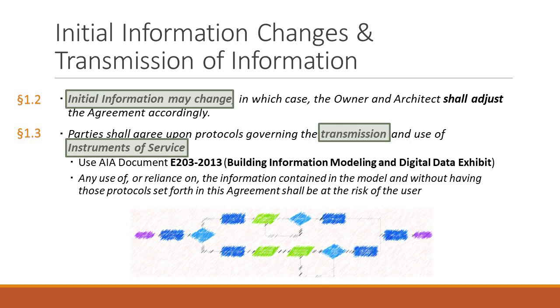Let's say that these drawings are uploaded on a Monday, and the contractor doesn't look, and they're working on a part of the project because they're looking at the drawings from the prior Monday. Well, since they deviated from the protocols and build something that week based on old drawings, and they haven't confirmed with the architect, and then the architect comes on the site and says, you're not building the right thing, the contractor cannot say, well, I'm just building it off the drawings. Because the protocol was every Monday, you need to check to see if there's been updated drawings.